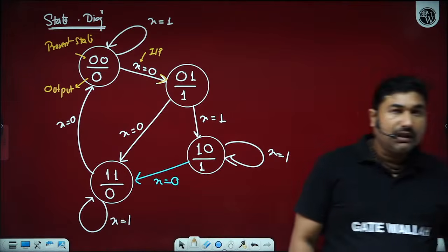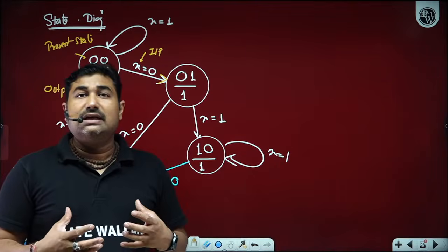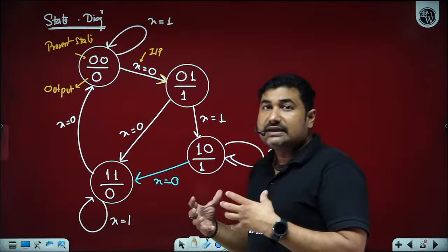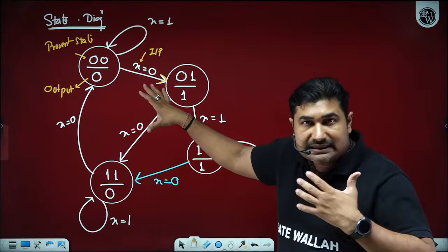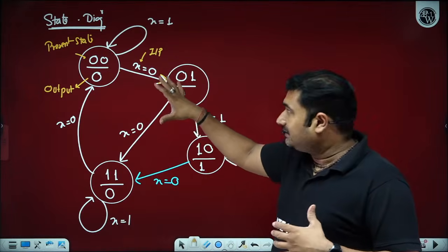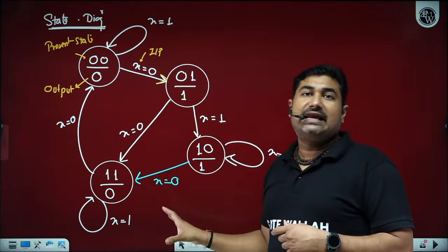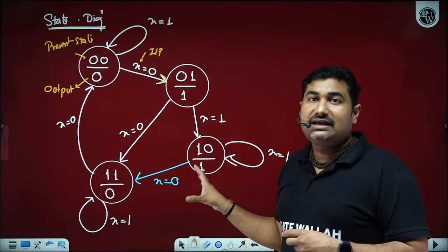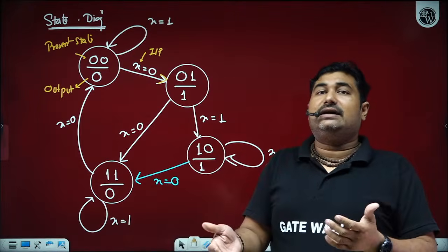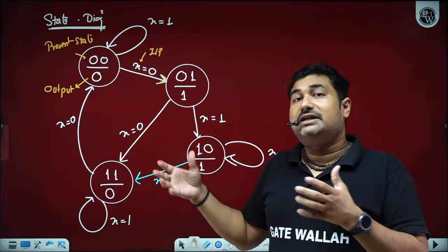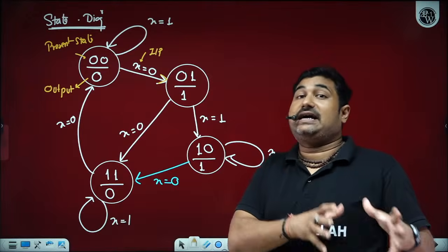Great. Next topic is state reduction. Whenever a user comes to us, he will set a certain set of conditions for what he wants to design. First we try to understand the desire, and then accordingly we first draw the state diagram. After drawing it, we check whether the conditions are repetitive, and then we draw a reduced state diagram.